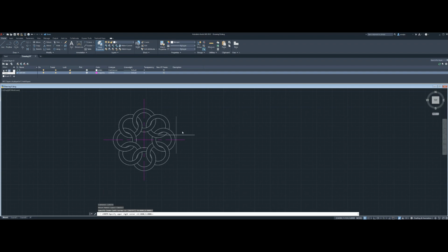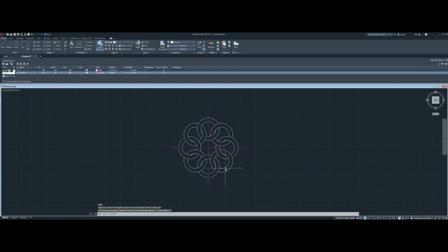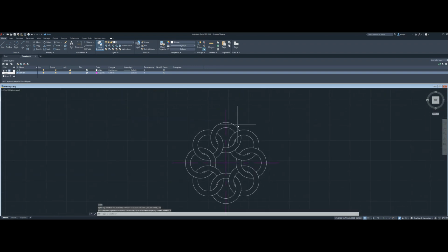Say here and up here. I specified the limits. It's important. If I zoom all to my limits, it basically zooms to my limits. I will re-specify them to make sure that the bottom doesn't get cut. And zoom all again. Okay.